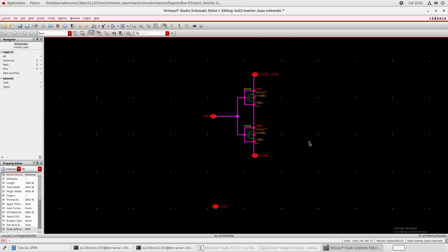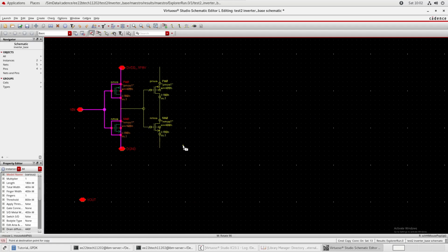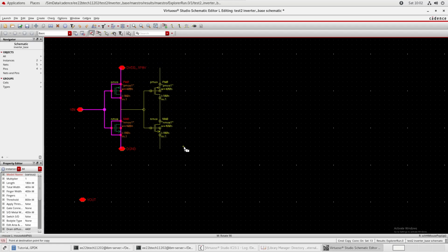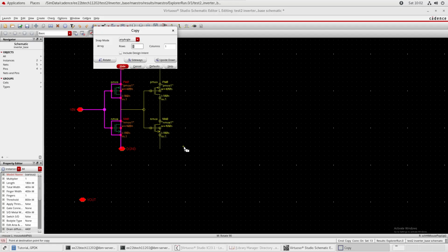Select all of this, then copy C, and then you can just copy it anywhere. Now this copying is fine, but while you're in the process of copying in this zone, you can press F3 and it will give you these advanced options for copying. So you can do copy at any angle, or diagonal, or orthogonal. Orthogonal is what you'll most probably see.